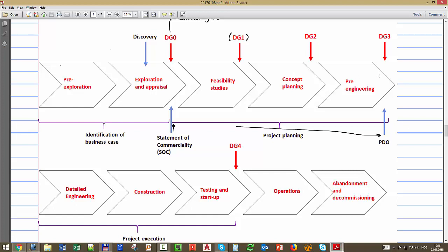You have to first have an overview of possible ways to develop the field. Then define all elements of what I call, and I'm going to show today, the value chain of the reservoir, how I'm going to deplete it. You have to say which offshore structure I'm going to use, when you are going to drill the wells, what's going to be the completion and the layout of these wells, the offshore structure, the logistics, how I'm going to transport this oil to the market, what kind of personnel I'm going to need, what kind of operations I have to make, etc.